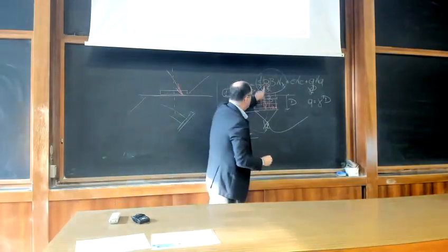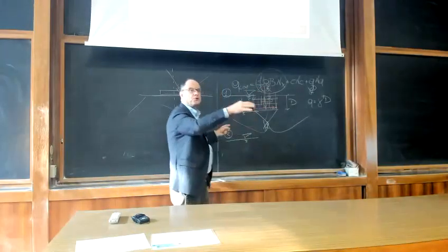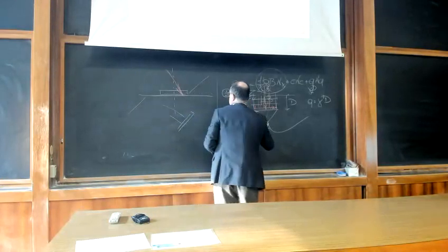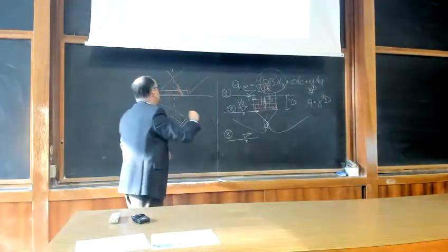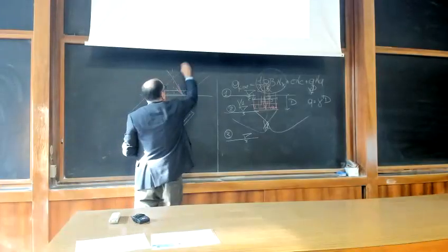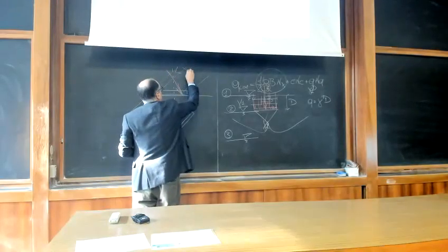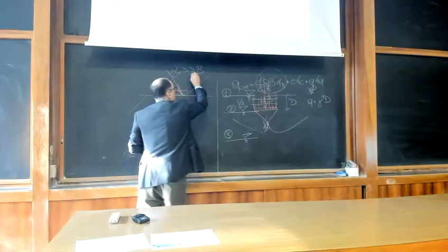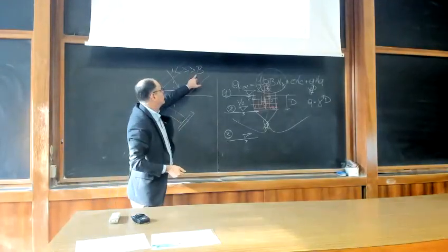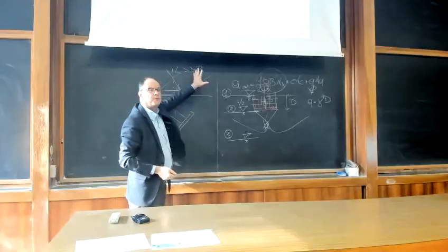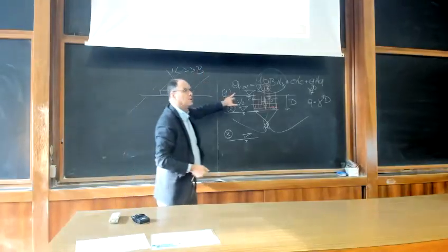This was assumed for a strip footing, so for a footing which is infinite in length, where L is much greater than B, because infinite does not exist, but when L is much greater than B, so this is a strip footing, you have the solution.